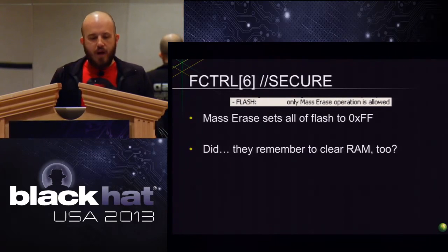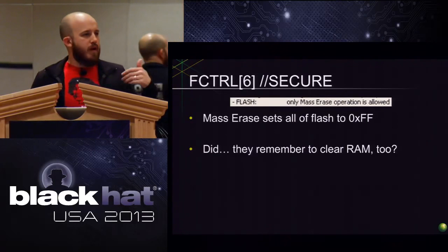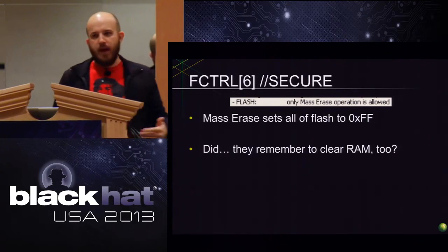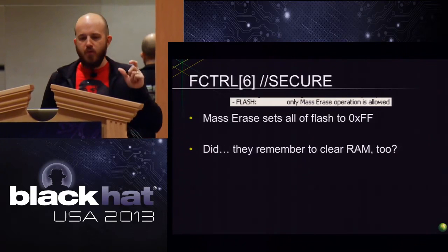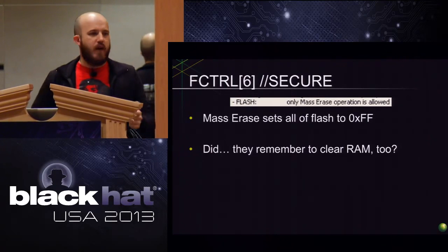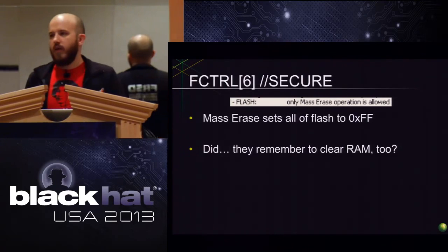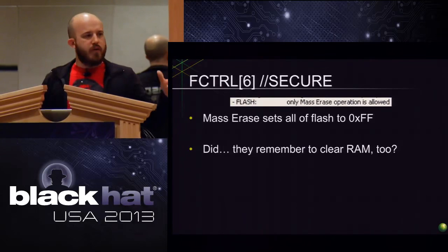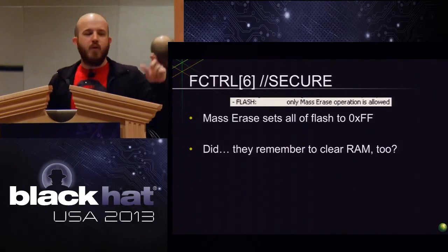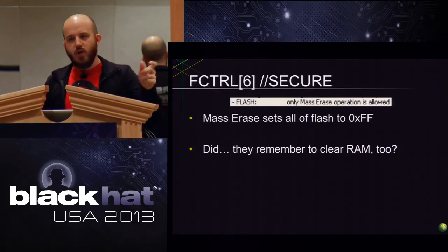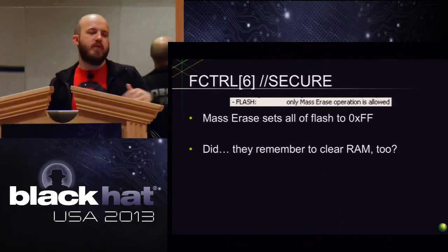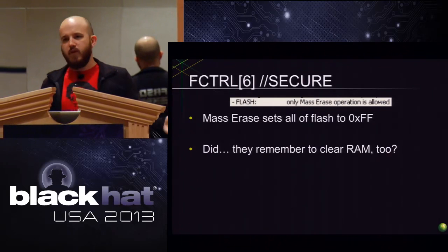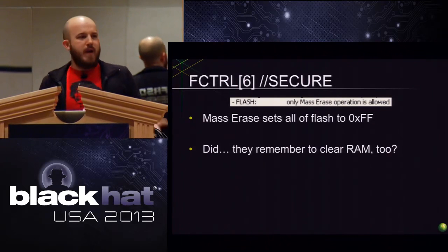The way to unset that. It's not a permanent flag, right? The way to unset that kind of stuff is to hit it with a mass erase so that you wipe out the code that is setting that in the first place. In the first 30 or 60 cycles, an instruction runs that sets this bit and says turn off the debugging interface, pre-boot phase ends, and then the debugging interface does not come up. So how do you get back into that device?